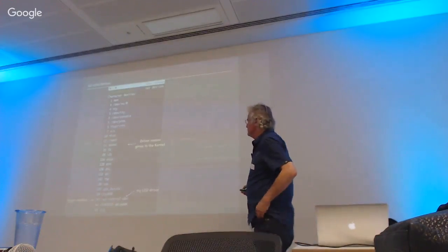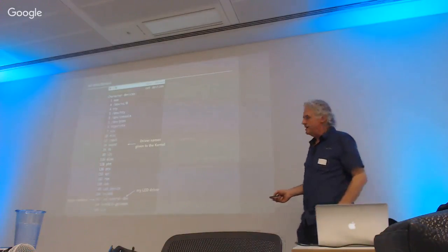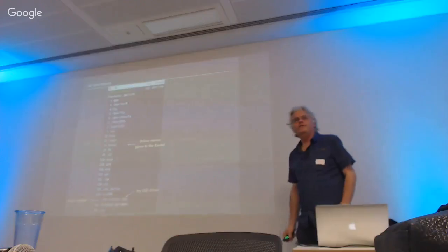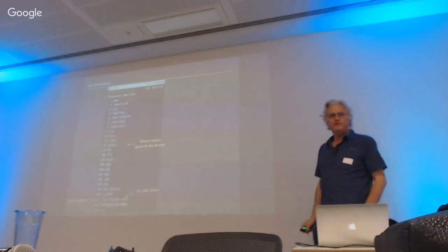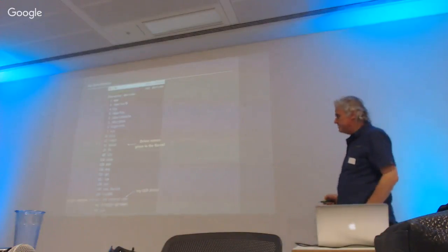These driver names, for example, here's a driver called Broadcom 2835 GPIO memory. It's involved in controlling GPIO pins. All these names are actually defined by the code in the driver itself. So I wrote a driver where the code is called LED control.c, but the actual driver name that I wanted is called LED control-dev here. That's my LED driver here.